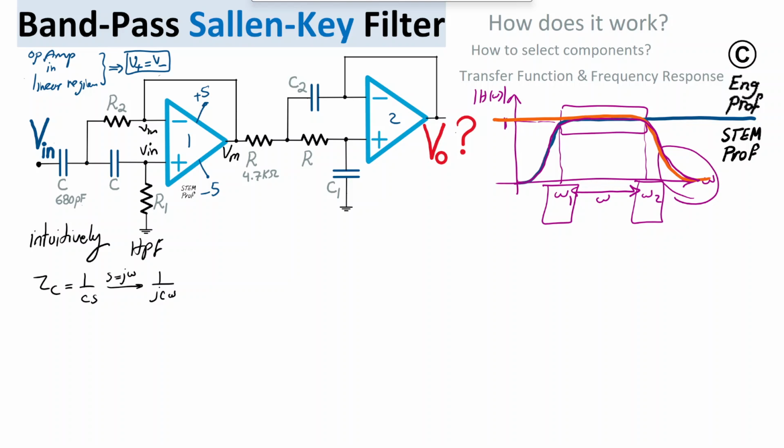So that means for, let's say, high frequencies, the first stage is effectively a pass-through. So Vin goes to the output directly without any attenuation. So for the first stage, as I talked about, at DC the output becomes 0, and for high frequency at the input, so this is Vin, this is Vout, actually Vin appears at the output as well, so Vout becomes equal to Vin. So that's a high pass filter.